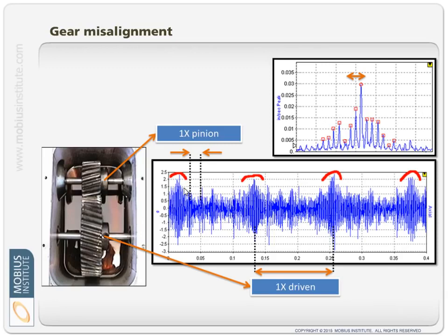That's when the lower speed gear goes through the mesh, how the forces change, and that's the higher speed gear. You can see the little pulsations in here. Now, the spectrum might show us this. These are side bands in the spectrum. We didn't really explain that, but it's actually very helpful. We see all these little peaks, called side bands. It means there's modulation. So if we do our spectrum analysis properly with enough resolution, we can see this. But we can see this for a lot of different reasons.